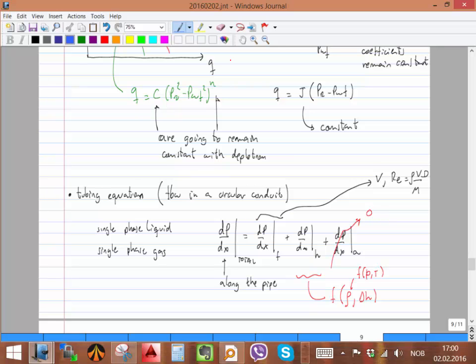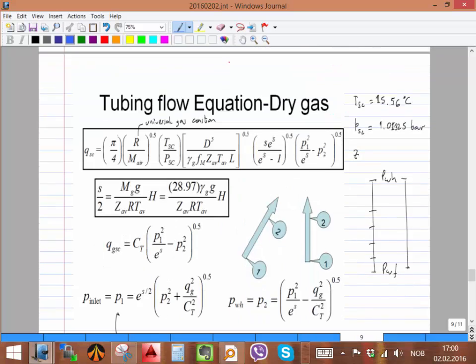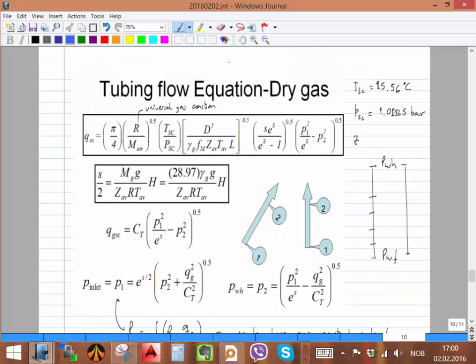Then to make a simple exercise, a single well exercise, I said, let's take the gas case. Okay, let's say reservoir with gas and also tubing with gas. We have a very simple equation, also very powerful. We took these two equations and we tried to find flow equilibrium using two methods. One of them is having the two systems of equations, clearing Q and PWF, or graphically using the solver.